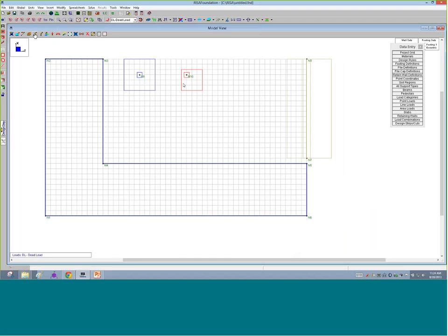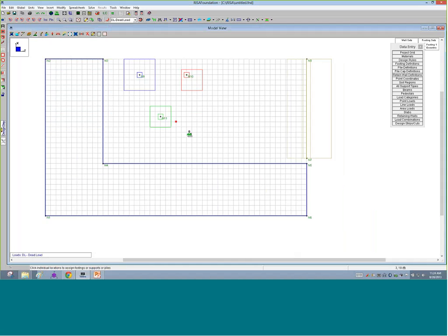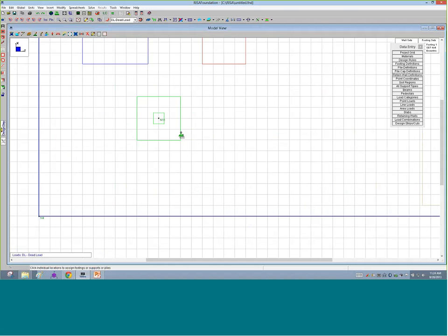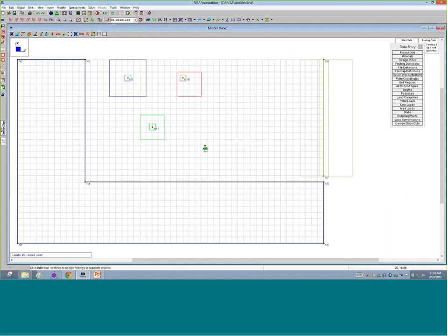And the other thing you can do is just take a look at that 4x4 that I created, and I can add a 4x4 footing. So now it's not going to size at all. It's just going to check that one. So you have some different options for your footings. Again, though, this is just for a point load, so we're not going to be doing a combined footing in this manner. It's just going to be a single point load on that. Actually, any different types of point loads, but it has to be a point load.